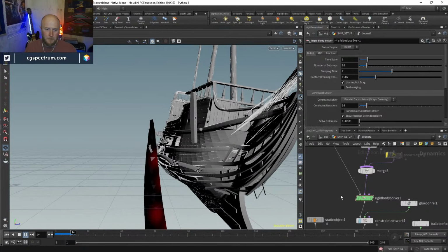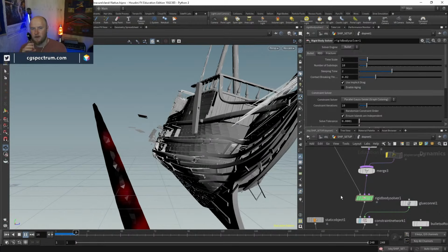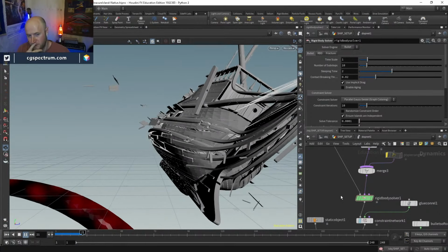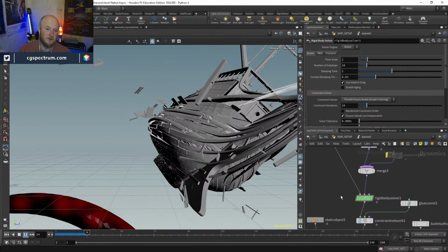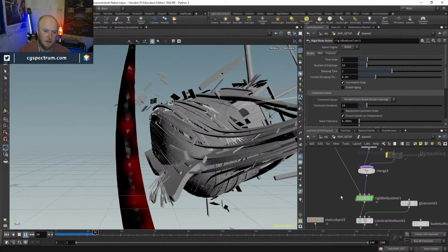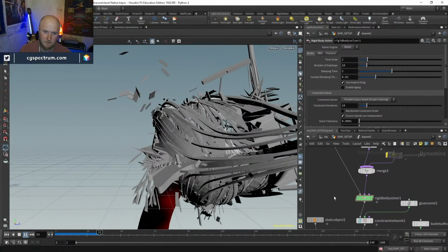Coffee break. So whenever you've got collisions that are moving really quickly like that, you either need to slow them down, but if slowing them down is not possible, then you need to potentially add extra substeps. You can see it didn't fix the problem.